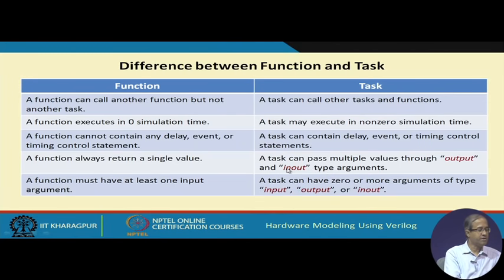Now, another kind of port declaration is there which I have deliberately not talked about. I shall take some examples later. These are bidirectional inputs, inout. Inout means you can use that variable as an input and also as an output. Okay? But when you map it to hardware, sometimes some problems are created for inout type variables.